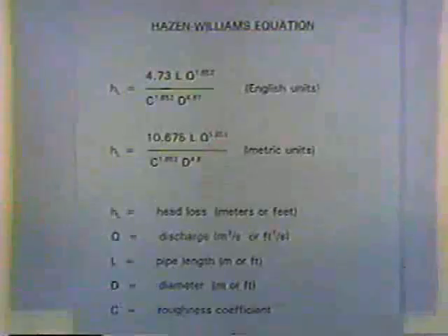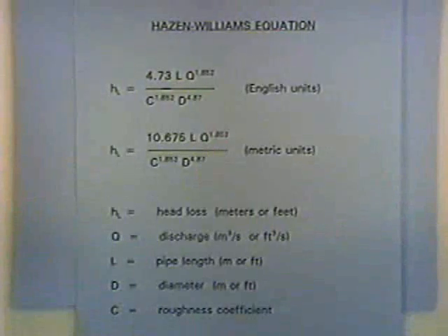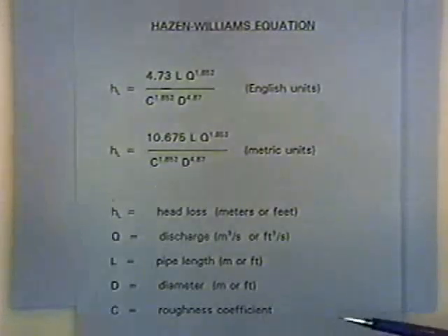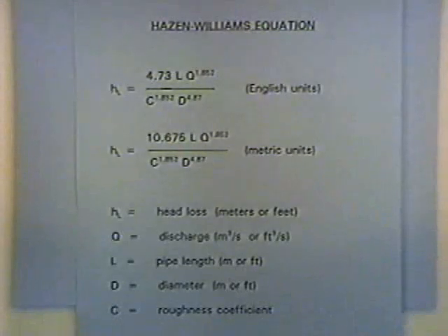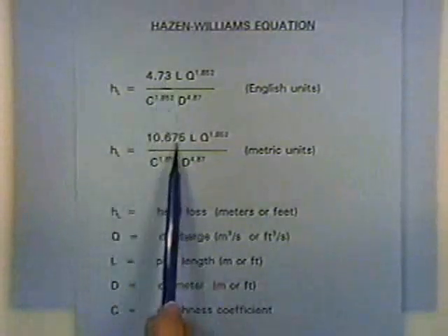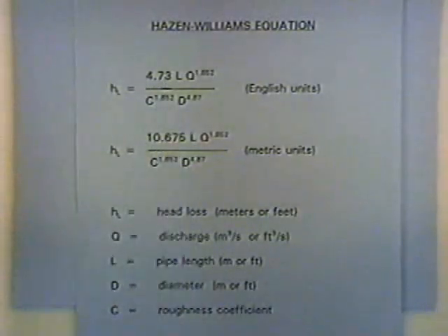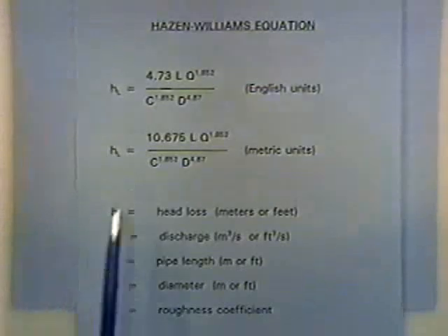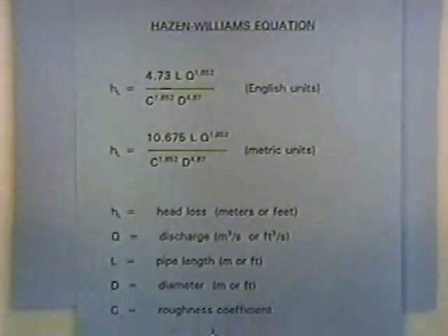Okay, the Hazen-Williams equation is another widely used equation for doing the same thing. And we've reproduced the equations here in the format that they're already in the form for the type work we're doing here with them, estimating head losses in a pipe. And so all the units, these are not dimensionally consistent equations in the sense that these constants have all the unit conversions lost in them. And so the length of the pipe needs to be in either meters or feet.